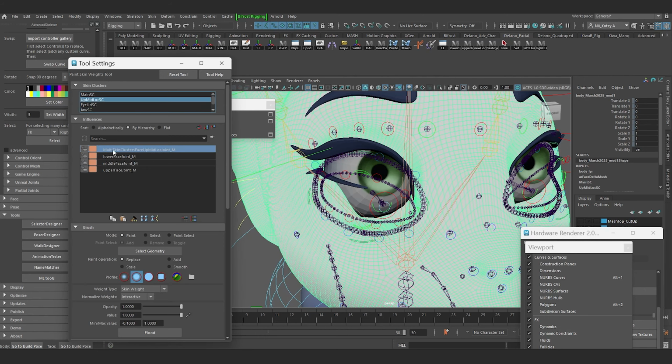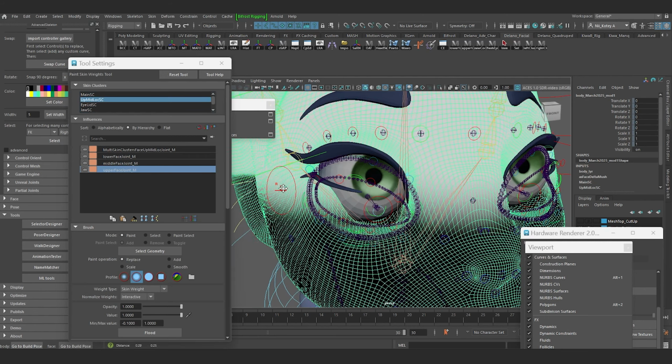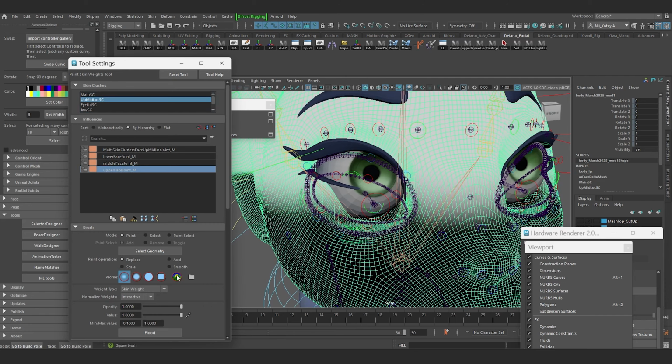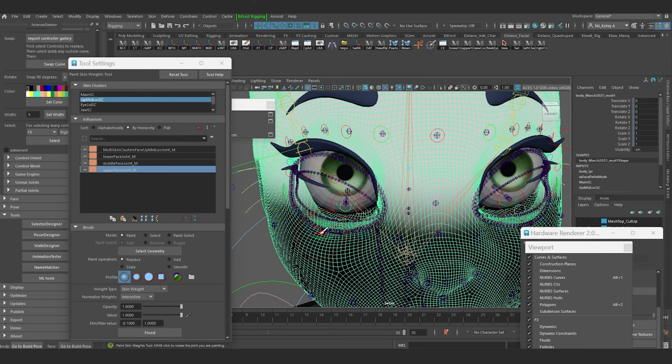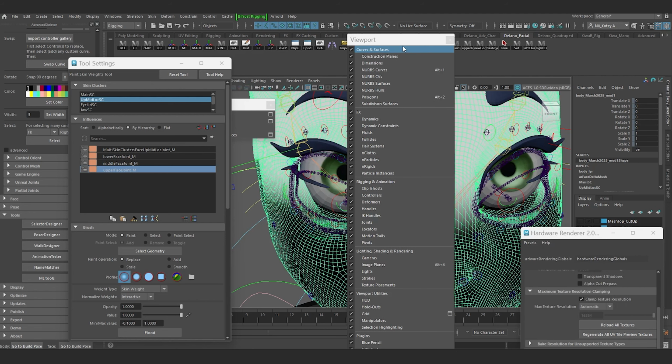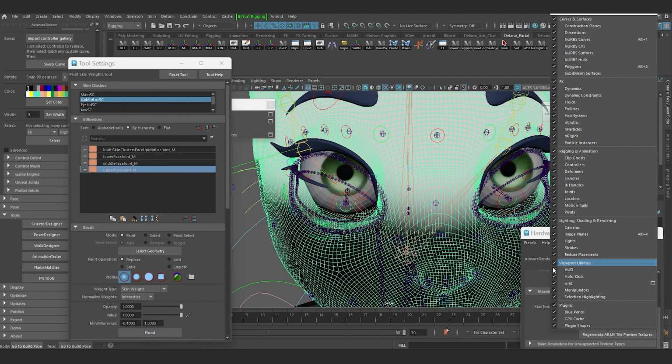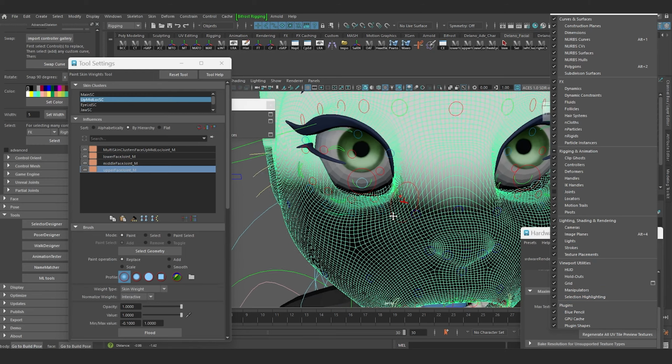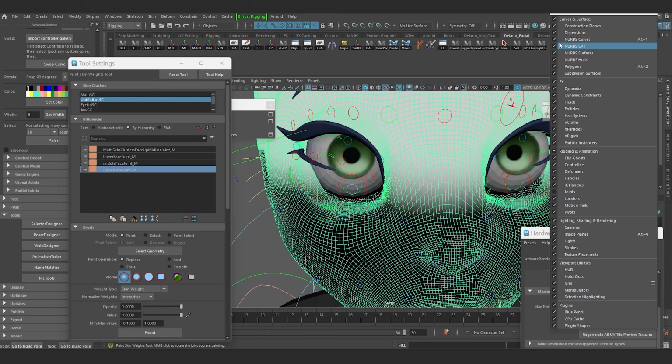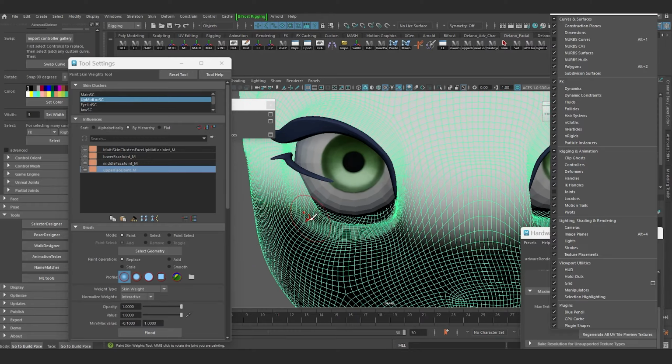So if I come over here, take the high, mid, low control, grab there, and I can grab my soft brush and start painting. Let me temporarily hide these joints because they're starting to look really messy, making a mess in the viewport. And also my nose curves temporarily.